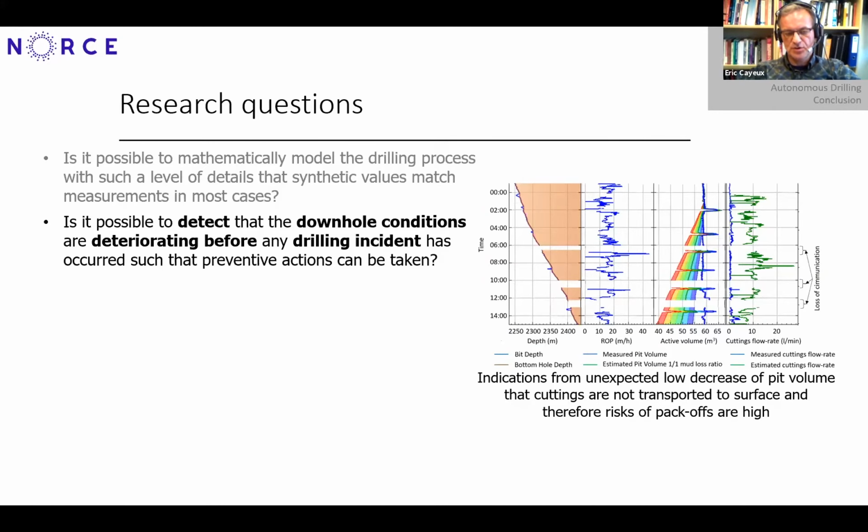We also want to be able to utilize real-time information to predict whether there is something abnormal coming into the well. Here is an actual operation. I will come back to that operation later in the presentation, where we could see that the cuttings transport was not performing at all as expected. We had almost no cuttings coming to the surface. And of course, when the drilling operation continued to drill for several stands without having any cuttings coming to the surface, it was quite likely that some disaster would come, and it did arrive.